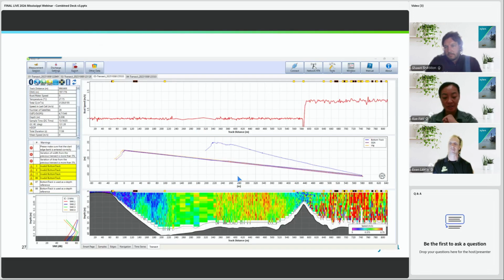So going back to the measurement itself, I haven't talked yet about why we have a forward and back transect all in one, sort of stuffed in one measurement here. The reason is because we actually had a faulty antenna on the M9 system itself. And so mid-channel, we actually lost communications with the M9. But we knew that the M9 had an internal recorder. All M9 ADCPs come with an internal recorder. As long as the M9 is pinging, it won't stop. And so even if we lost communications, we just kept going.